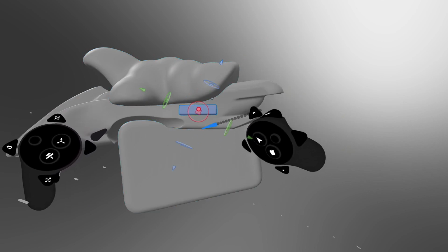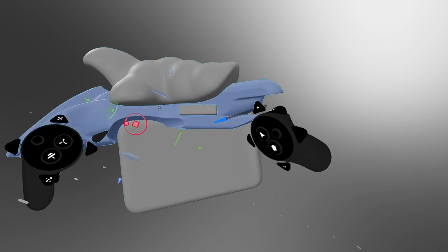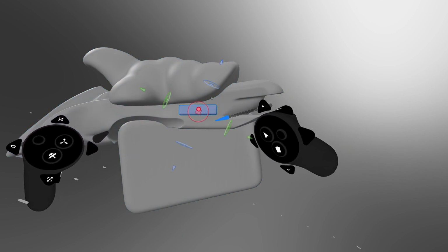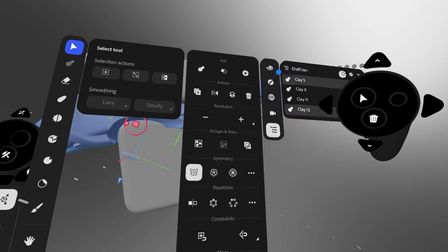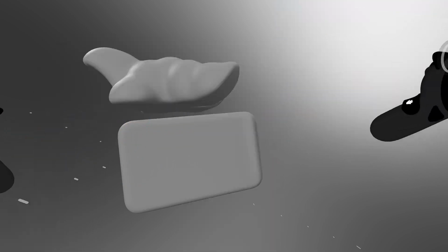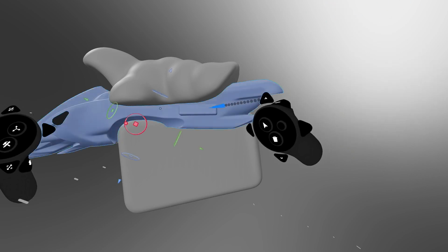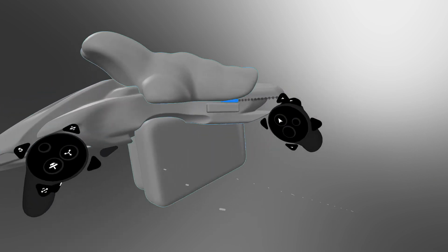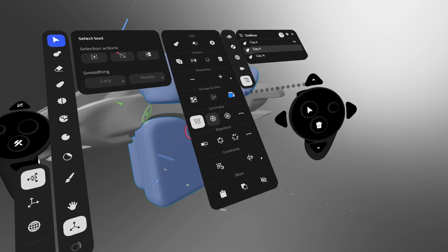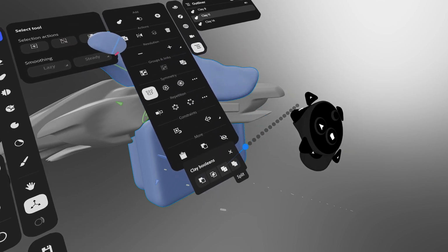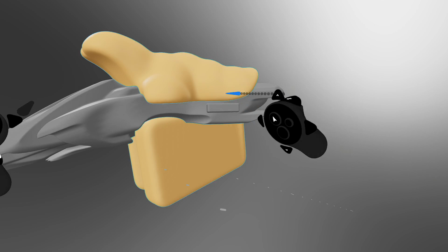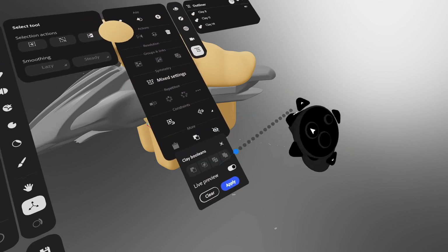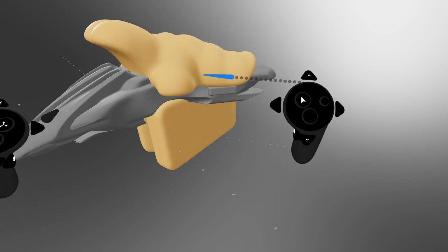We'll see. Anyways, so that's a separate object, right? This is the whole reason I was doing this. This is a separate object. If we just select that one and this one, we can go in here and we can just merge. So that's more or less like a Boolean union. It's done, you know, so if you're ever curious, that's the faster way of doing it. This one, though, we're doing a Boolean split. All right, it's going to show up like so. And unfortunately, you have to click apply on it like this to actually perform it.